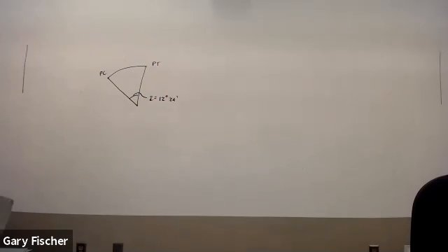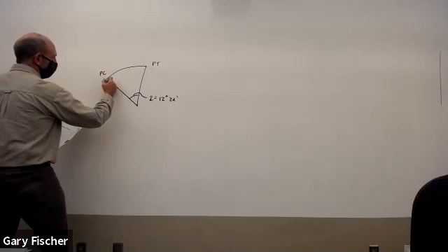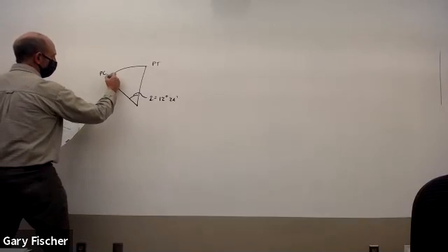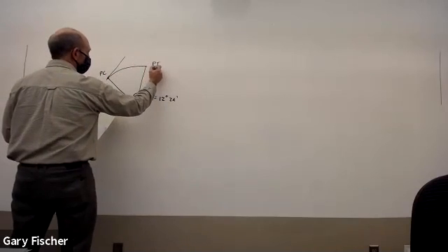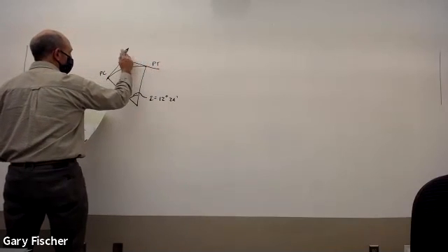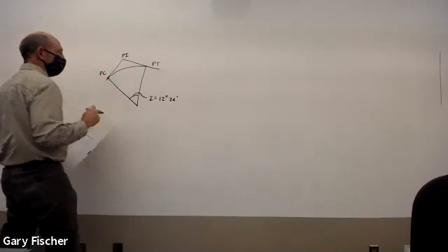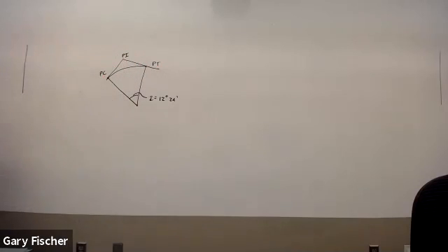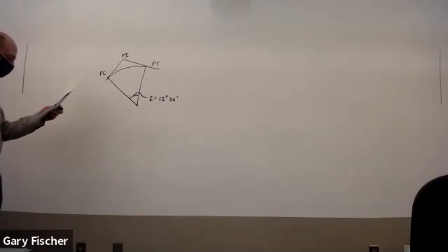Now they have a PI. A PI means that you're running a tangent line up from your PC out to here, and another one from your PT out to here. It meets at this point up here that they call PI, or the point of intersection. Okay. Let's see.